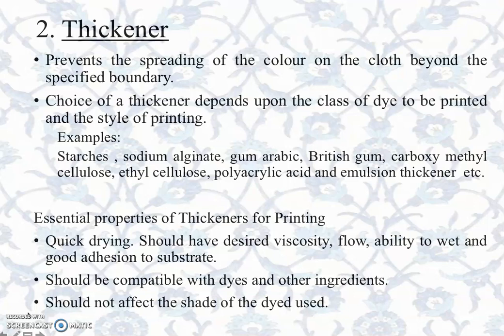To achieve an even print, there are certain essential qualities of a thickener. It should dry quickly. It should have the desired viscosity, flow, and ability to wet, and should have satisfactory adhesion to the fabric after printing and drying. It should be compatible with the dyes and other ingredients present in the printing paste. It should not affect the shade of the dye used.